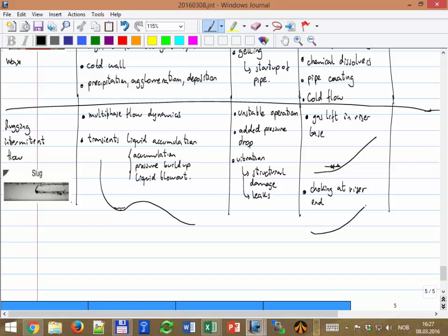You put a choke here, and then you choke to control the slug flow. And also another option that we didn't mention yesterday is subsea separation. Again, an area under development, but in theory, if you have problems because of having these two fluids, you can just separate them, having the liquid and the gas separately, and pump and transport them separately.